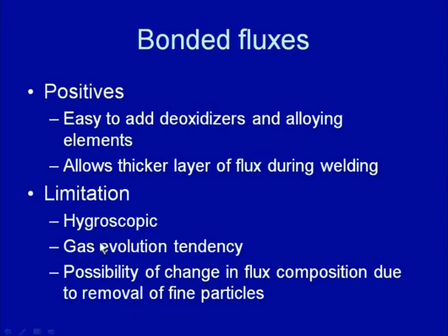Further, the presence of moisture and other constituents leads to easy evolution of gases from these fluxes during the welding, and there is the possibility of change in flux composition due to the removal of fine particles. So, this is another problem, where there will be a possibility of change in flux composition if the fine particles are removed from the fluxes during the storage or during the handling. This is another limitation related with the bonded fluxes.